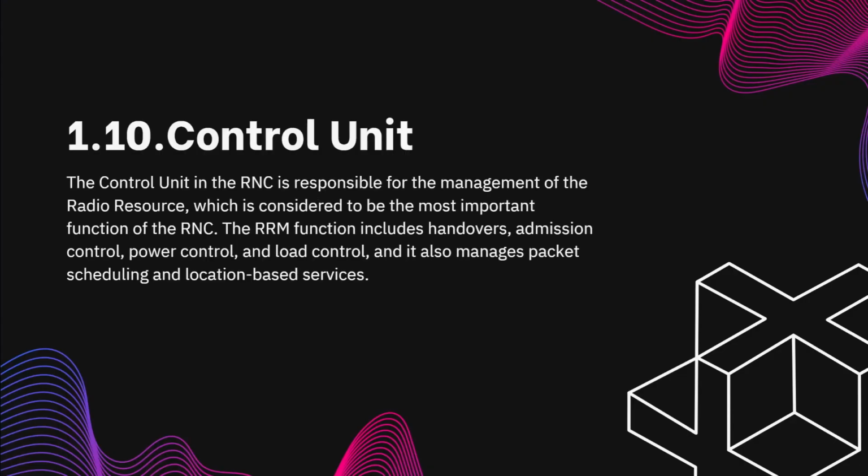Next is the control unit. The radio resource management, which is called RRM, is widely regarded as the most crucial function of the radio network controller, as it affects all three network planning entities: radio, transmission, and core. The control unit of the RNC plays a significant role in RRM functions such as handover, admission control, power control, and load control. It also manages control mechanisms for packet scheduling and location-based services.